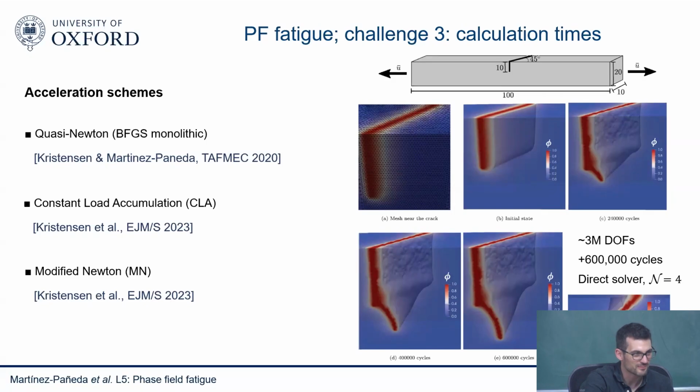Yeah. If we can reduce the convergence criteria, maybe. We haven't done that because, well, you never know. When you start playing with convergence criteria, sometimes it's good, sometimes it's bad, sometimes you deviate from the real solution, and then you struggle to recover it, and it's worse for convergence. Yeah, I guess one can play with those things. I don't expect big gains on that front.